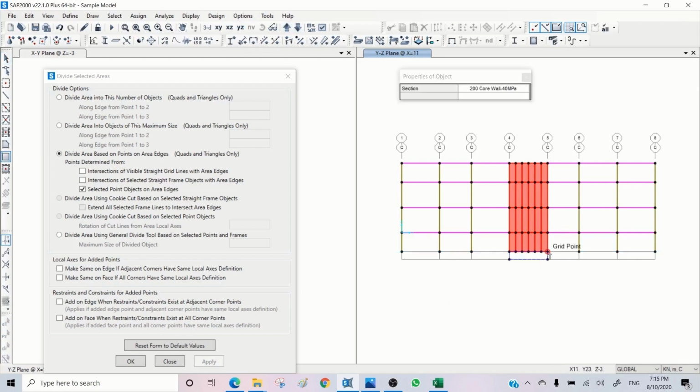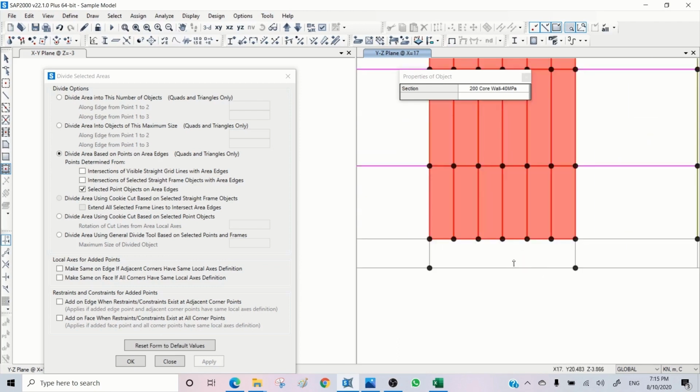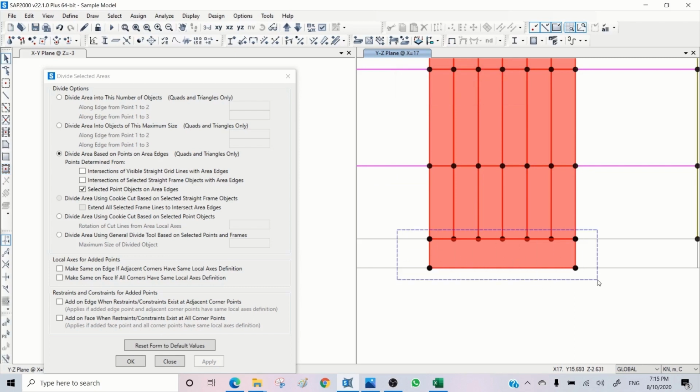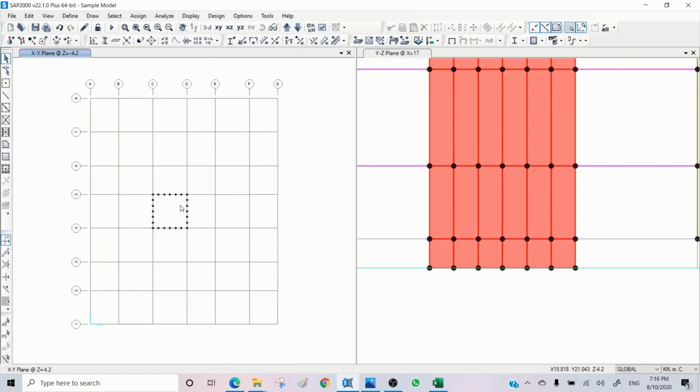And just select this joint and apply this command and move. You can use quick frame, just need to ensure that this is correct. So you can come in front and then press here and again do the same, apply. Okay, so my lift pit wall is modeled now. Now if I come to the plane and move down, I can see the lift pit wall.